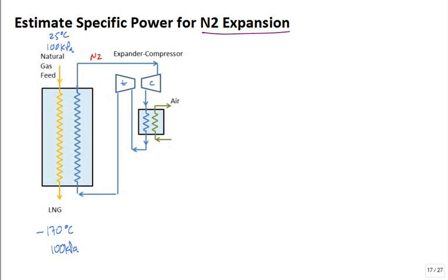And then you put it through the countercurrent heat exchanger. Now, as engineers we do have to worry that the nitrogen is always going to be colder than the fluid in this countercurrent heat exchanger, but I'm going to just ignore that. I'm just going to say it's cold coming in. Okay, how cold do you think this nitrogen coming in has to be? This is the hard part. You're an engineer. Could it be negative 150? Negative 100? Is that going to work? What temperature do you think the nitrogen coming in is?